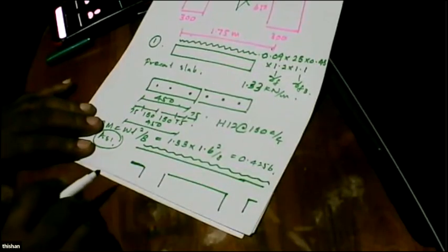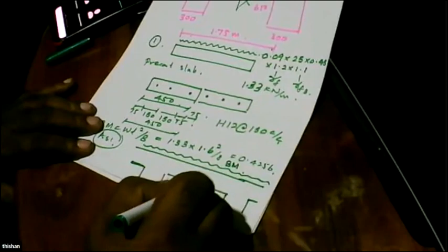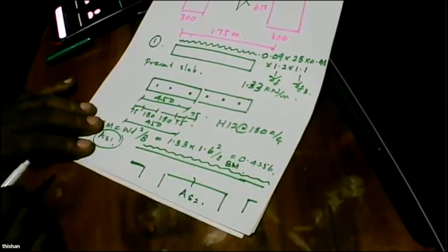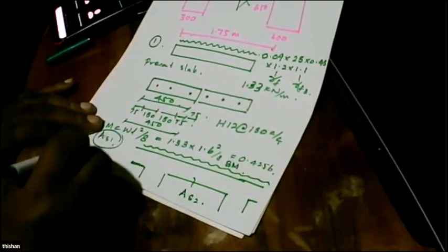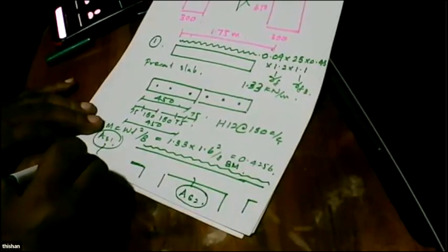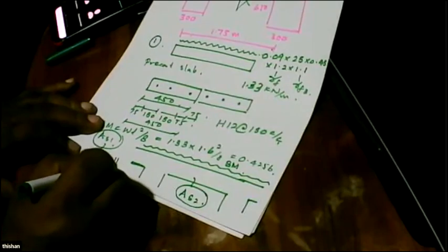Due to those live load moments, you are going to get another bending moment, and for that, you can find the reinforcement AS2. So when you are providing, ensure that what is provided covers AS1 and AS2, AS1 for dead load plus self-weight.